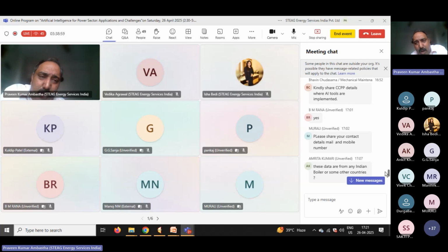I will take your plant geometrical data and the process data of the plant, and by simulation of the digital twin, I will be able to tell you that your surface heat transfer coefficient has deteriorated and the surface is dirty, so you require soot blowing. So one of the criteria is dirtiness. The second is time, then reheater metal temperature, sprays and so many things, and of course cost. A fuzzy logic is being used for this, which is very successful, and we shall be able to guide you on when to do the soot blowing.